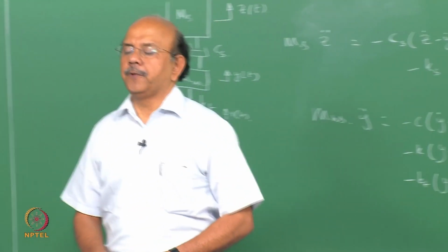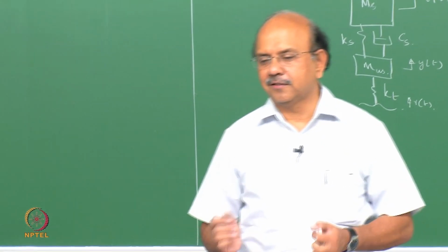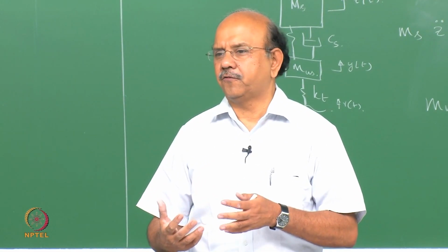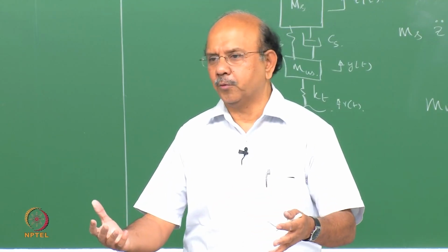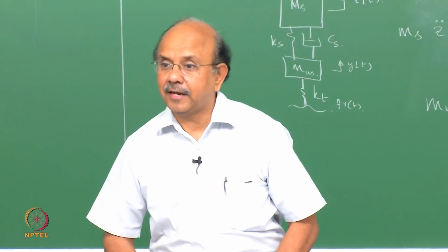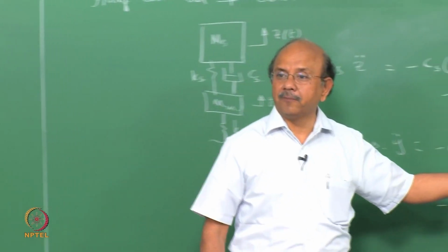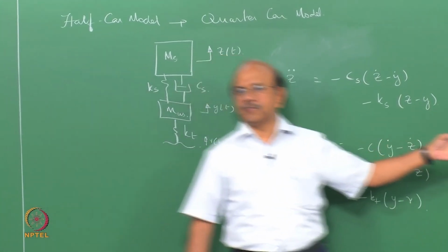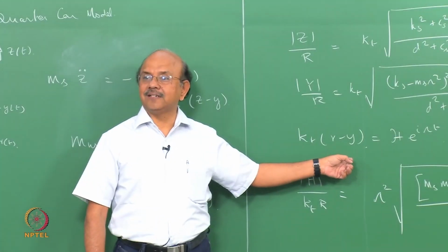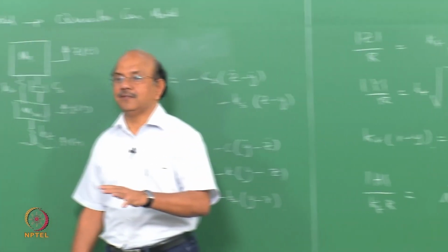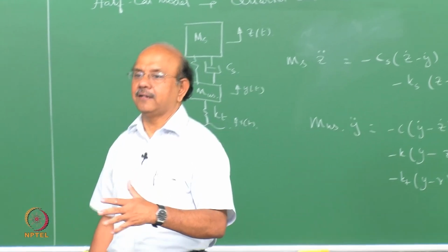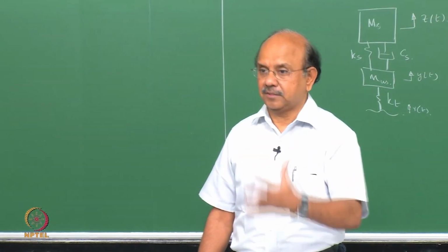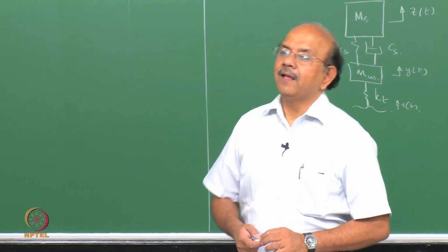So people feel that the best way to handle this is to ask what difference it makes. If it's not much different, then I will remove it. In fact, in the next step I'm going to look at the natural frequencies, and even in that case I'm going to remove the damping in order to calculate the natural frequencies of an undamped system. Okay.